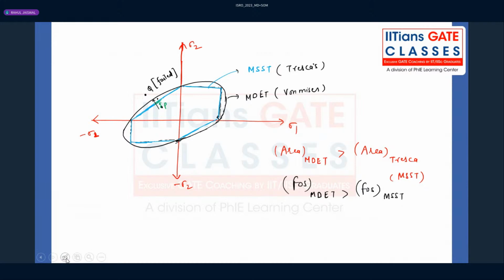Then von Mises is saying that you are very far from the failure lines, don't take a larger diameter, you can apply any amount of load, right? He will be giving you a very high factor of safety, and the one giving you the higher factor of safety is basically fooling you, not alarming you for the worst conditions.